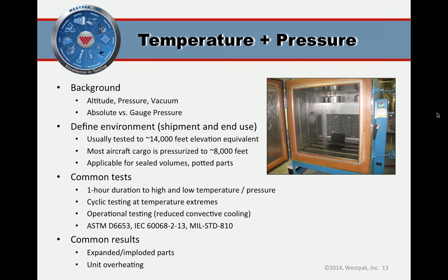These are very applicable for anything that has a sealed volume or potted parts where there might be air trapped inside, sealed packages, that kind of thing. It's also good to think about your end-use environment, though. So that might be much more severe, either much higher altitudes, or you may have high pressures. If you could use your product when scuba diving or in other submersive environments, think about all those pressures or low pressures and what those are and try to define them.